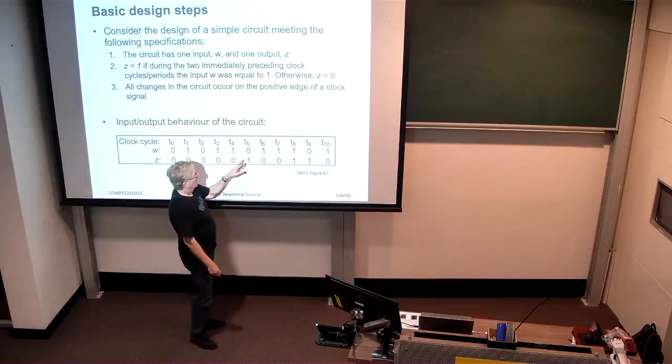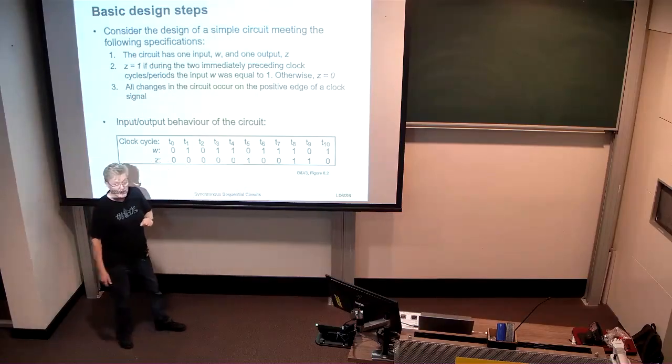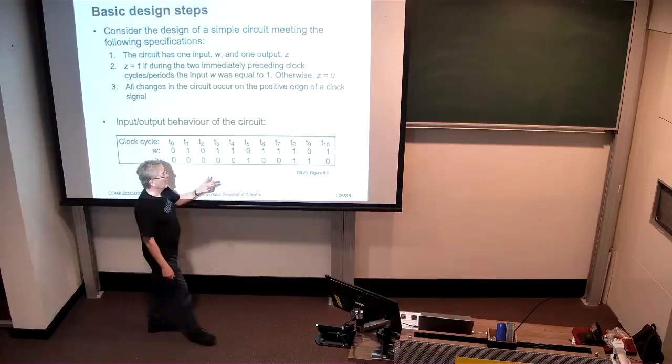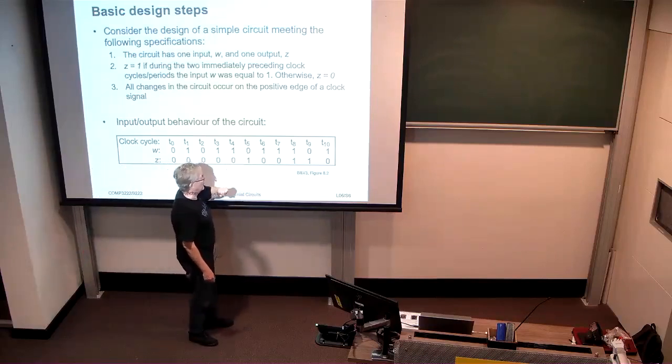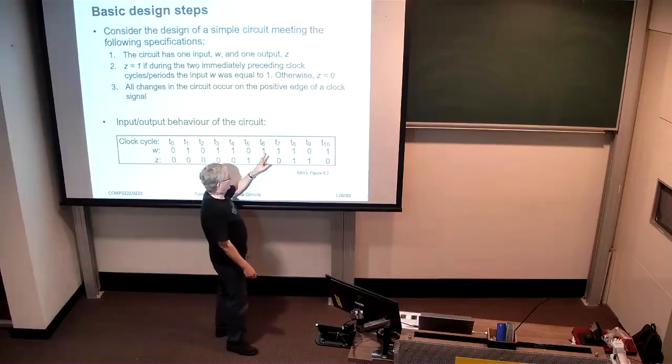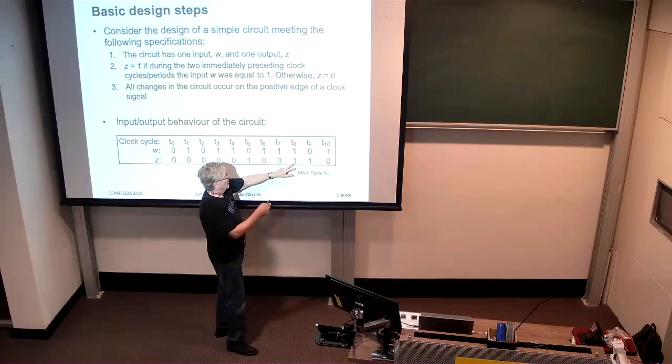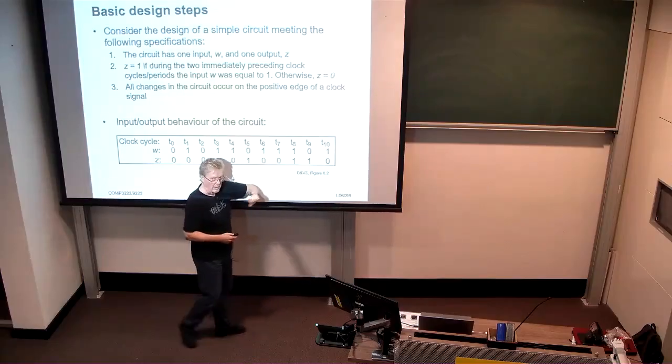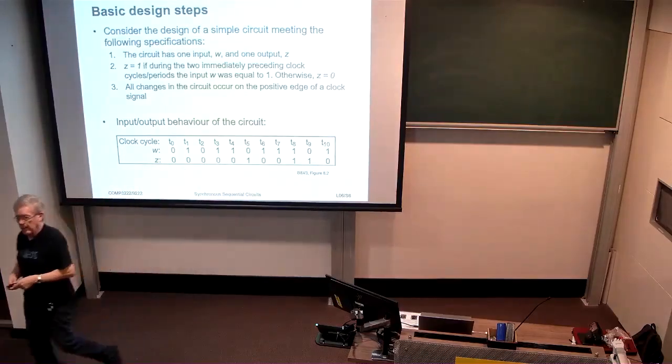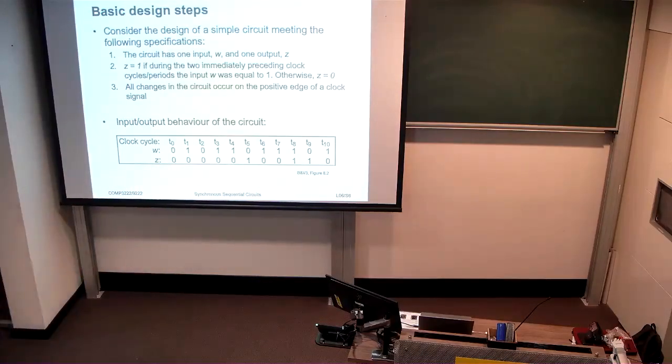We also observe that it goes back to 0 because there's a 0 read in the immediately preceding clock period, T5. But after T6 and T7, we see the output going back to 1. And because there's also 1 in T8, the preceding periods T7 and T8 force a 1 in the output in period T9. Okay? Are there any questions about the behavior of the circuit here?